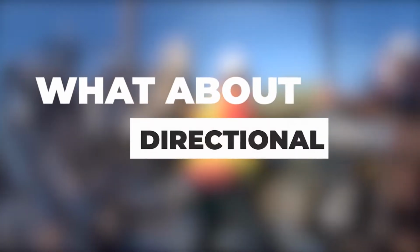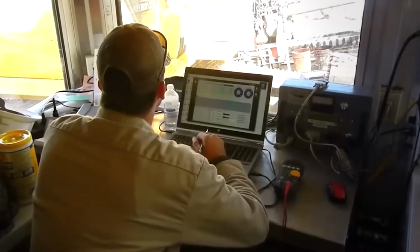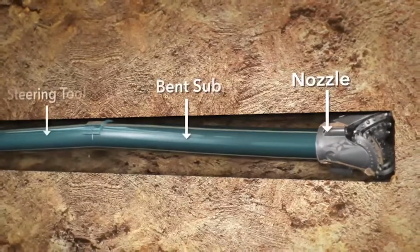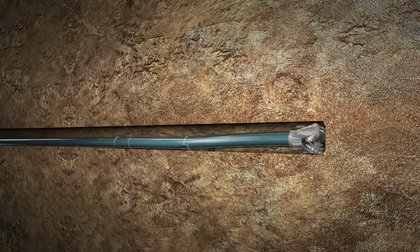What about horizontal directional drilling machines? Horizontal directional drilling machines, HDD machines, are steerable trenchless drilling rigs for the installation of pipes, conduits, and cables underground in a shallow arc. They are typically used for installations beneath rivers and roads to avoid disturbing the ground. Horizontal drilling machines are typically heavy-duty vehicles fitted with track drives, operator controls, and drilling rigs.